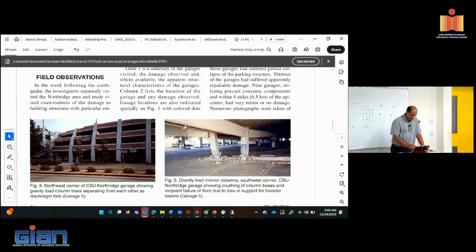So these are all indications of what they were trying to develop. In all of this observed damage, the structure is trying to behave like the strong-column weak-beam concept, because that's what was instituted, but the connections were not robust enough to hold on to it and eventually caused failure. The emulation concept, what we talk about as emulation, basically works fine in the non-seismic region.